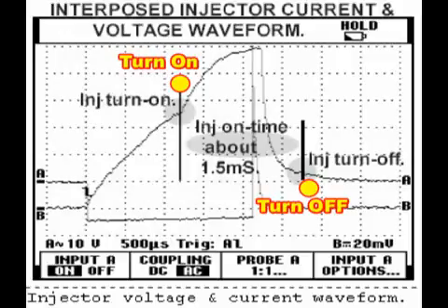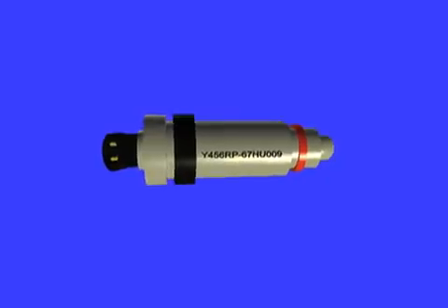If the spring is weak, the injector waveform closed hump will show up late. If the pintle channel is clogged, the open waveform current hump will also show up on the waveform. The oscilloscope test is the fastest way to determine a possible injector problem. Use the ATP scope 1 to capture the waveform and analyze it. Don't forget to finalize your measurements with an actual manual injector leak-down procedure.